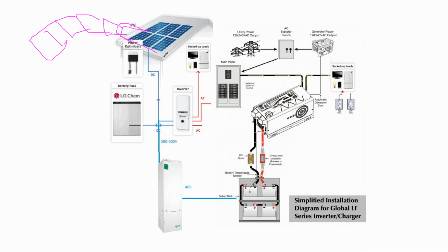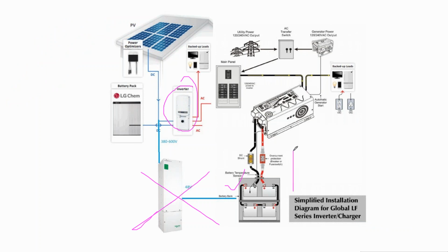So a short circuit of panels would turn the inverter off, but a long circuit of panels would just act like it was an overcast day as far as the inverter is concerned. And then this charge controller, as soon as the battery bank was filled up, would go away and all the power would keep going through the regular inverter.